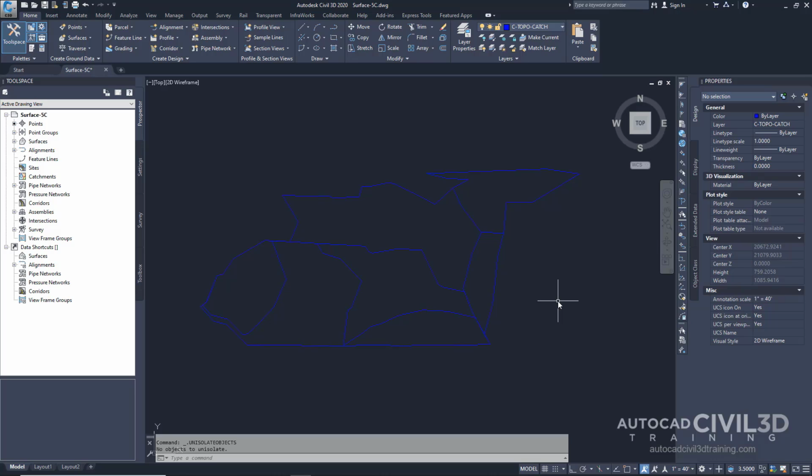Now this is a tip: you can transfer individual or shrink-wrapped catchment area polygons to a hydrology application for further analysis. So that's how you go about analyzing surface water runoff in Civil 3D.